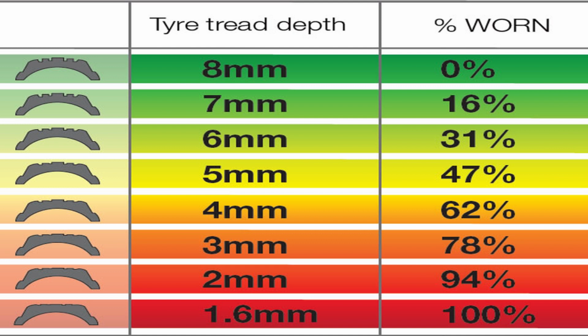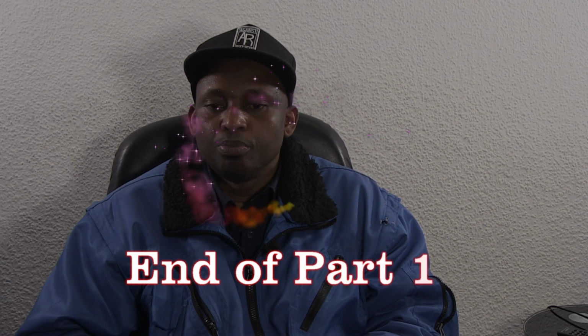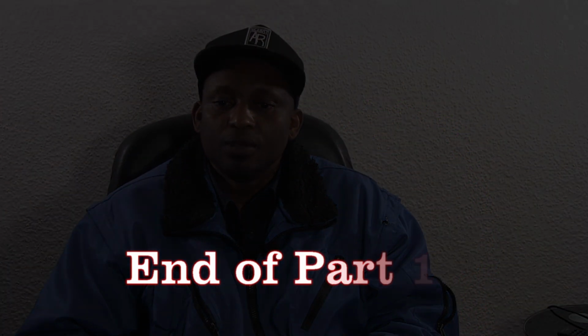Please, when this tire is now lower than 1.6 mm from that indicator, where those points are, I will show you in the next picture, you may put a measurement from there, something to measure. If it is lower than 1.6, it's no longer secure. Anything can happen when you are riding it. So I will take you to a picture to explain what I mean by that.